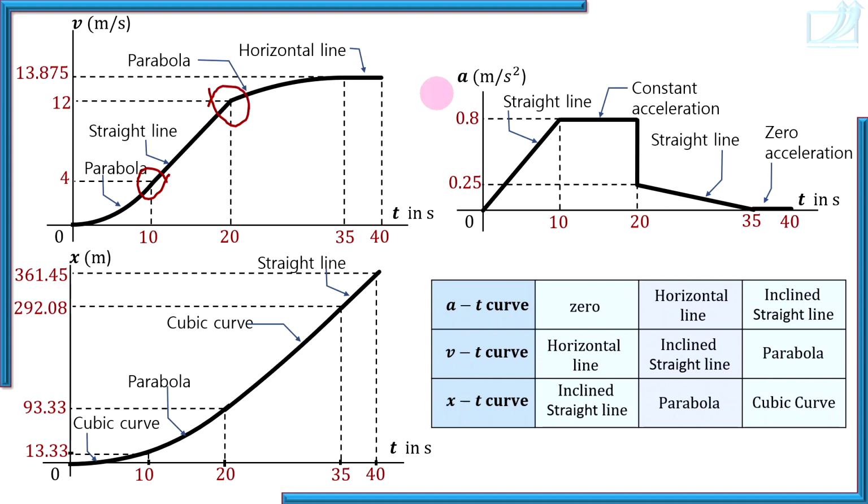So remember those 5 points I have given you initially, and knowing those points you will be able to draw AT, VT, XT diagrams easily. Of course, a little practice is required. Read all those solved problems I have given you and you will understand it better.